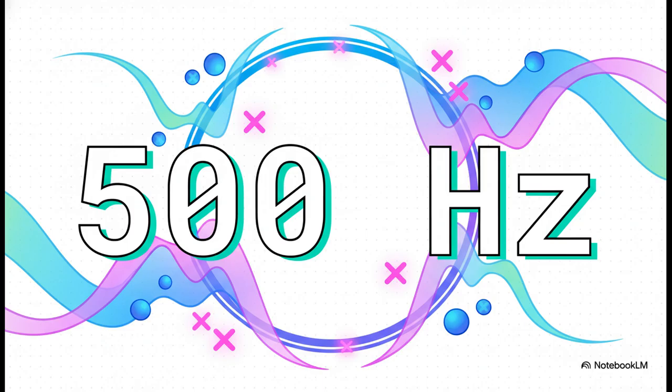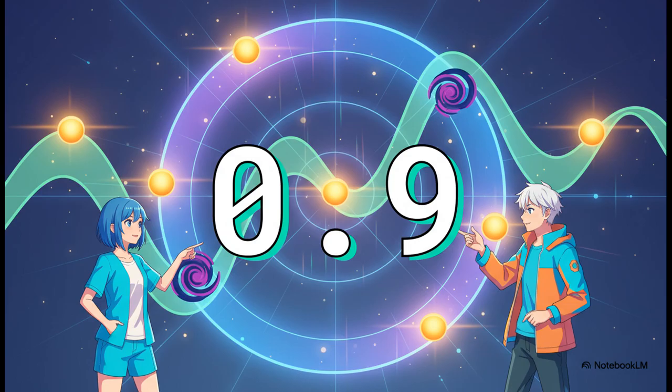Now on to step 3. All right, step 3 is the radius, R. Let's pick a value of, say, 0.9. Now that's not super close to 1, so it won't be insanely sharp, but it's not close to 0 either. It's going to give us a really nice, well-defined peak, a perfect starting point for boosting that 60 Hz signal.